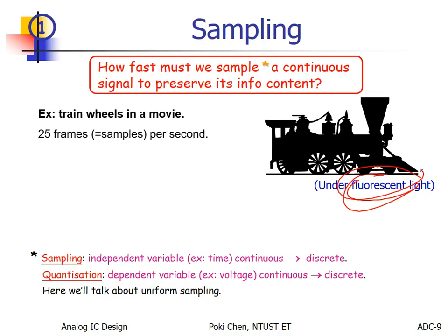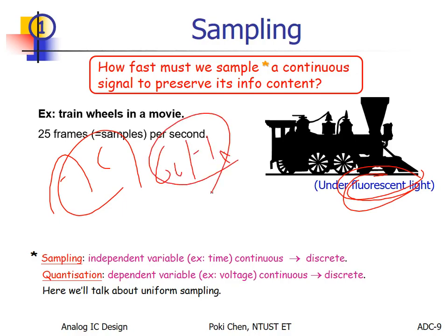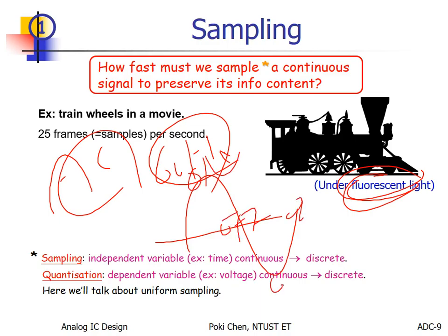它会闪烁. Yeah. It is powered by AC electricity, so in Taiwan that is 60 hertz. For such kind of AC power, at the peak and at the bottom it will be turned on, and in the middle it will be turned off. So the blinking rate is 120.